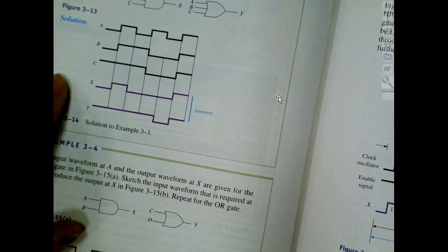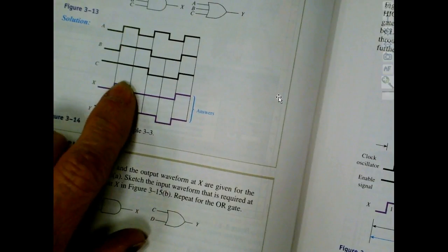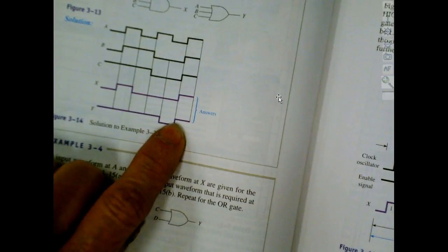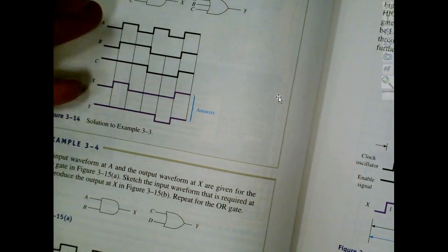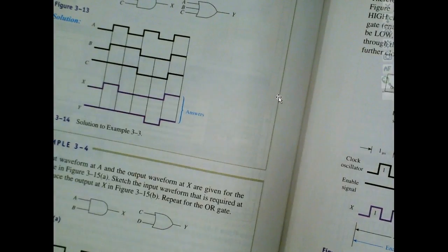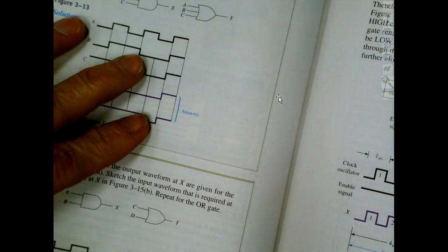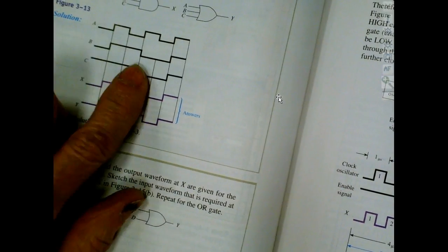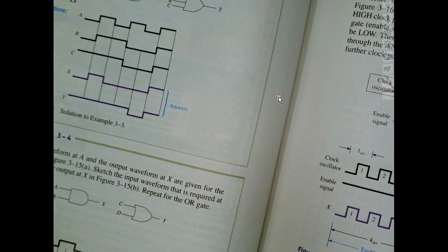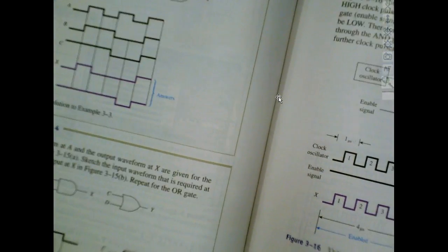So this is the timing diagram for a 3-input AND gate. This is the timing for a 3-input OR gate. But it's not a truth table, right? And if you can do this, then you understand that gate. Because this is what we would see on an oscilloscope, right? You know, if this was the pattern on the input, or a logic analyzer would be better. Are we okay?